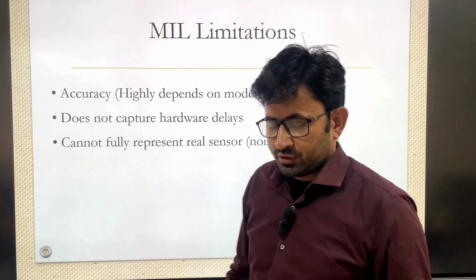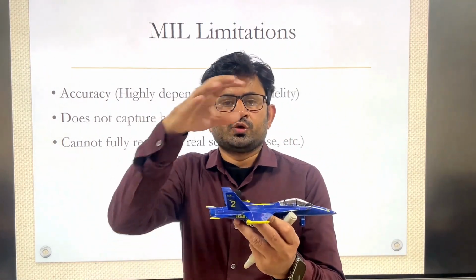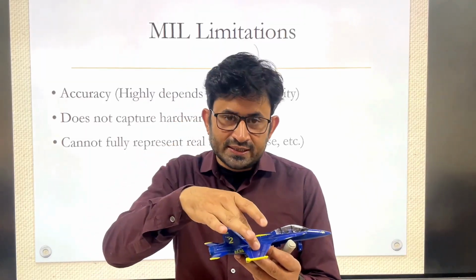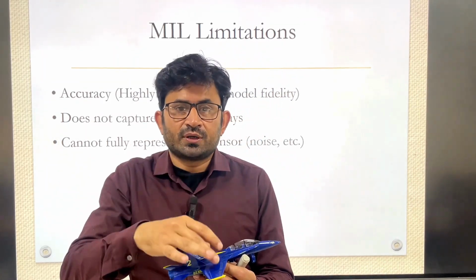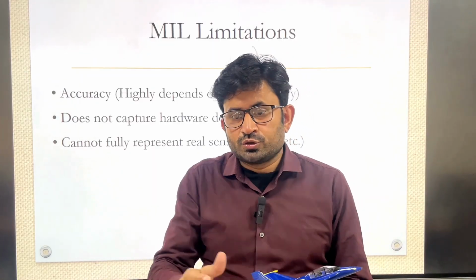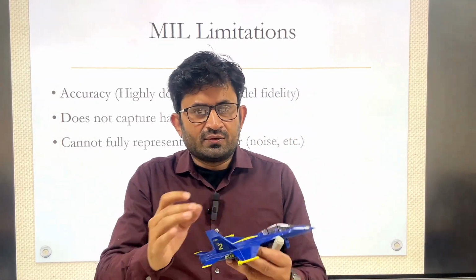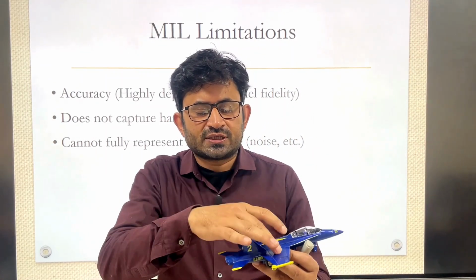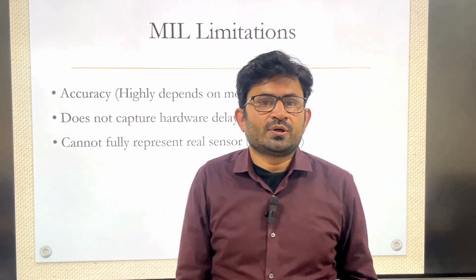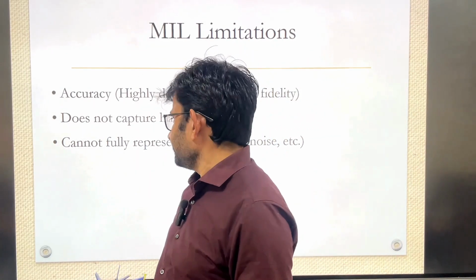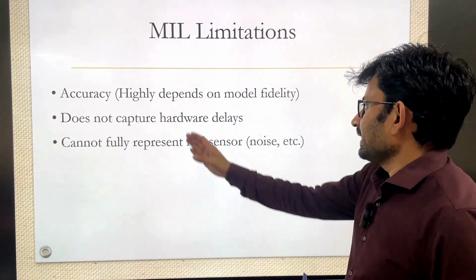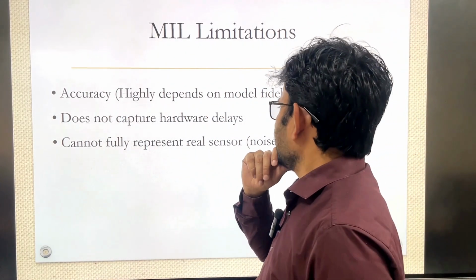Okay, because let's say this is the aircraft you have modeled in Simulink, and your controller is modeled in Simulink. So in this aircraft, the aerodynamic model, propulsion model, all the models are sitting, and if the modeling is incorrect, then this model which you are analyzing, and based on whose response you are designing the controller, will also be incorrect, because this is a model dependent controller, right? So accuracy is one of the problems. Okay, it highly depends upon the model fidelity.